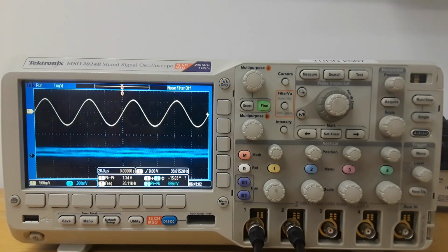And we can see our input appear, a sine wave. Looking at the bottom of the screen here, you can see that the peak-to-peak voltage on that sine wave is 1.36 volts. The frequency is just around 20 kilohertz, wandering between 19.9 and 20.03 or so. Meanwhile, on channel 2, we can see that the peak-to-peak is a lot smaller, and really we're just seeing a lot of electrical noise there because nothing's coming out of our signal processing board yet.